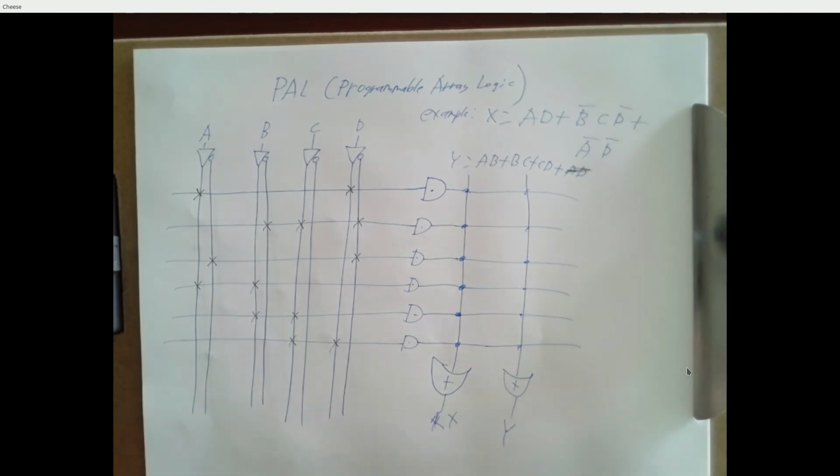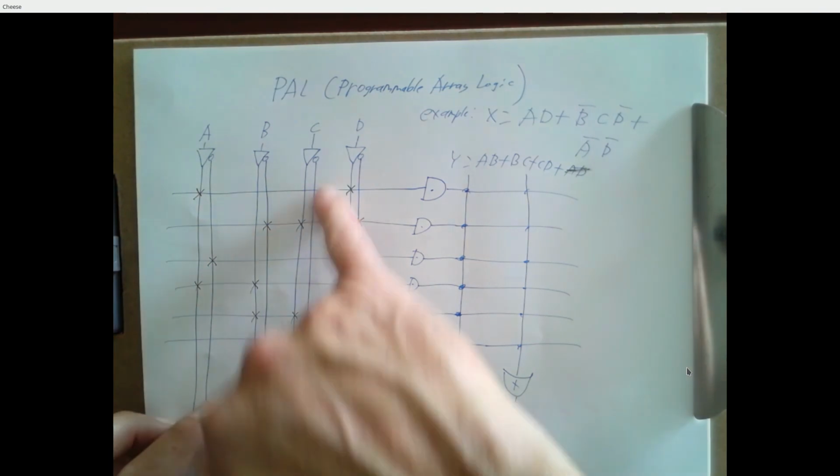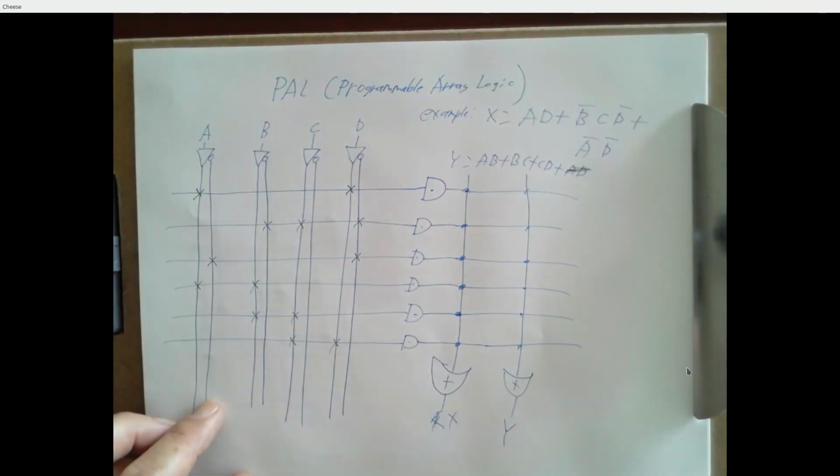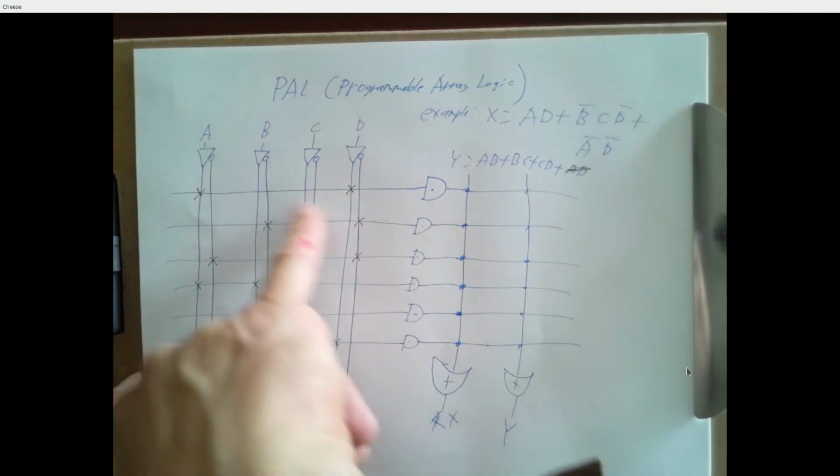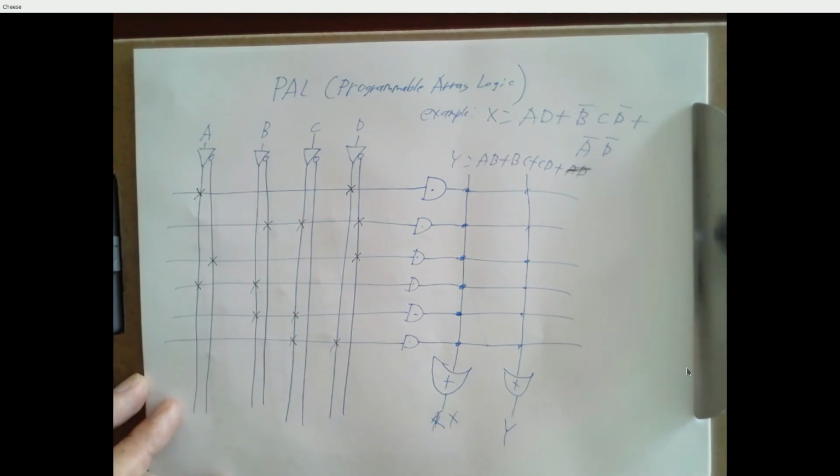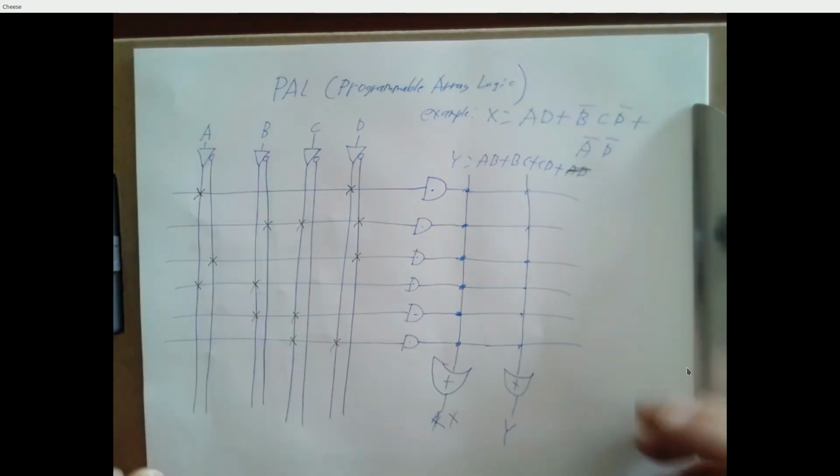So this is generally called programmable logic. And this is a little 20-pin chip. You plug it into a programmer, and you tell it where you want the connections to be, and it will go through, send current through each of these fuses in the right way to melt the ones you don't want, and leave you with a chip that's been programmed to implement your functions.